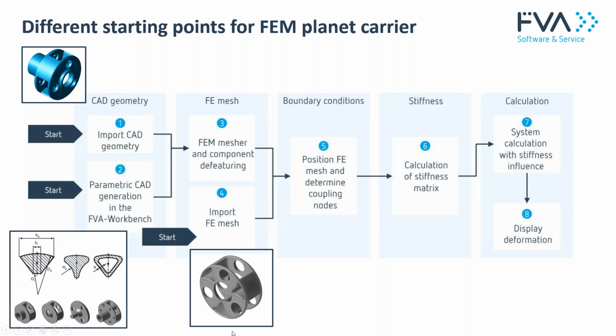The third option to start is from an already existing FEM model, so an FEM mesh. This might be interesting for you if you have some meshes from your calculation department. You can directly import them in the FVA-Workbench and couple it, starting from here, to the remaining model.